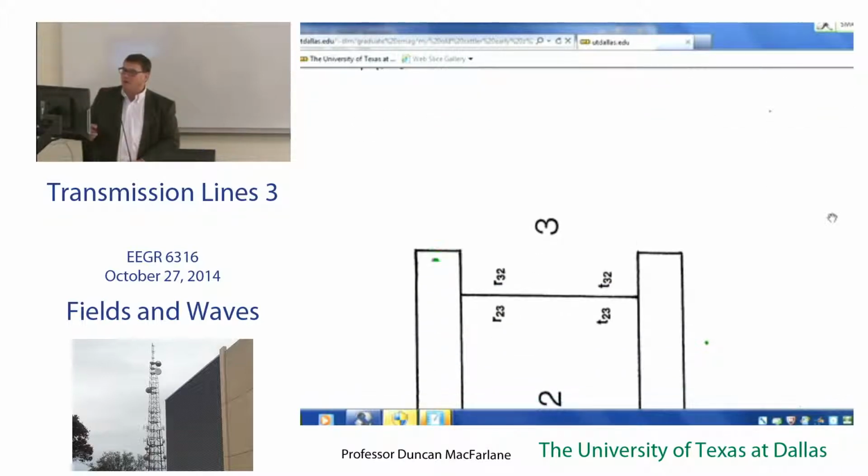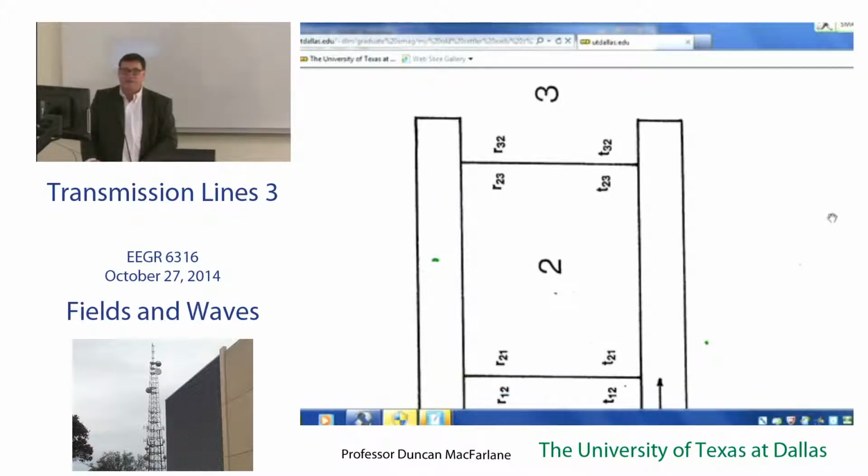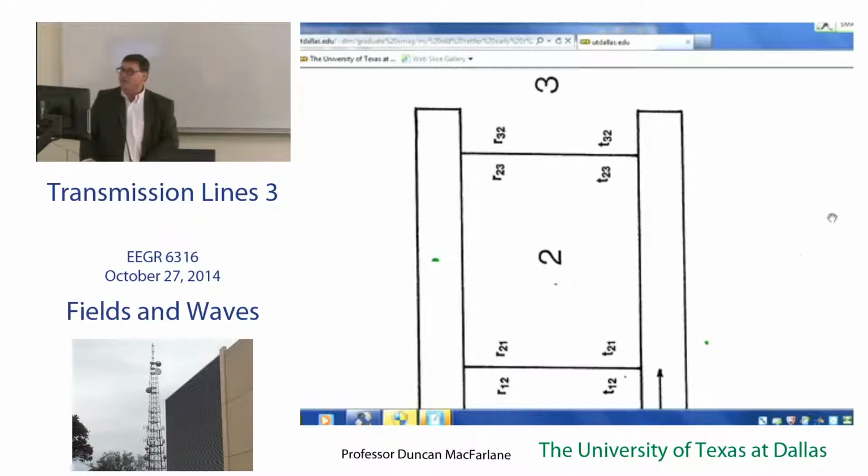Now, like I said, once we have this algebra, we can now add mirrors. Remember that I was adding mirrors before with the delta function response or the multiplier response, and I had to think of some very complicated algebra tricks in order to solve those problems. And I was wasting a ton of time just doing the algebra by hand. Well, as soon as you have the signal flow diagram, you can add mirrors all day long to your structure, and the algebra just follows really mechanically. And it's perfectly amenable to a MATLAB implementation. So it's so nice and clean.